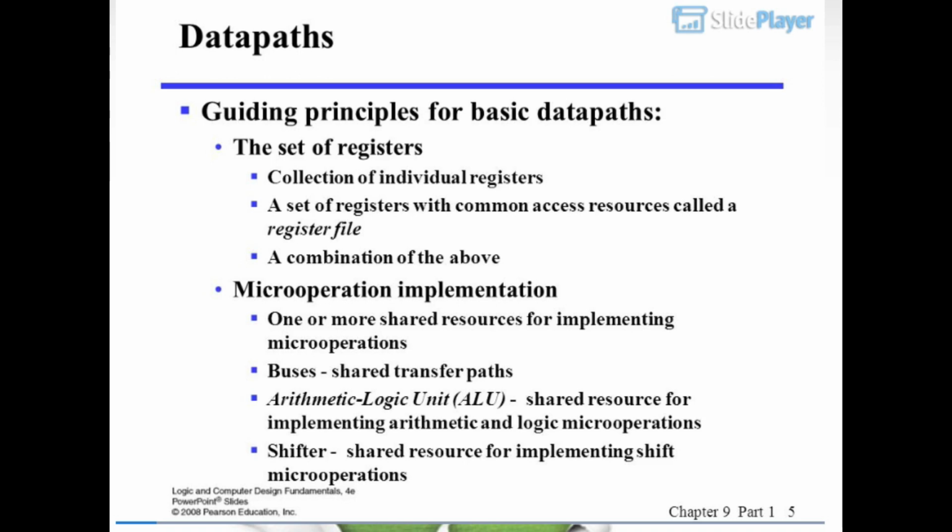Collection of individual registers. A set of registers with common access resources called a register file. A combination of the above. Microoperation implementation. One or more shared resources for implementing microoperations. Buses, shared transfer paths. Arithmetic Logic Unit, ALU, shared resource for implementing arithmetic and logic microoperations. Shifter, shared resource for implementing shift microoperations.